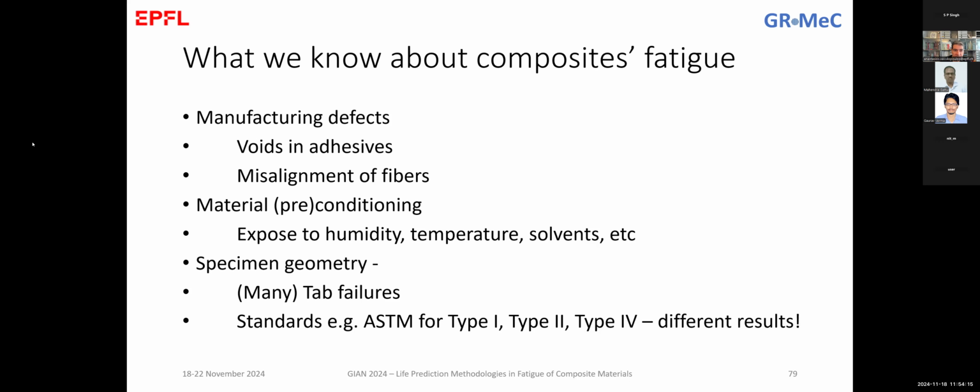Here I can start a short diagram again. I can plot the material property, either strength or stiffness, against the angle of the fiber orientation. Imagine that you have a lamina with fibers in this direction, and a lamina with fibers in the off-axis direction.